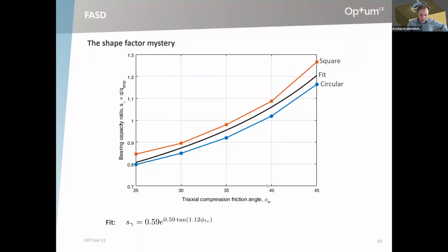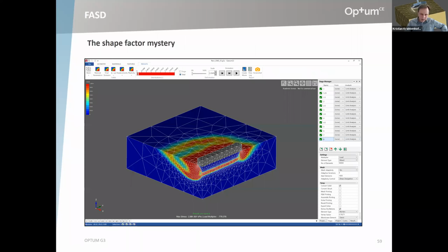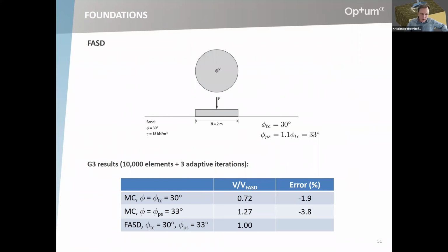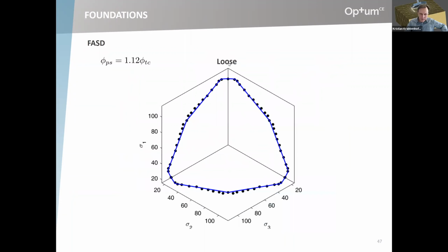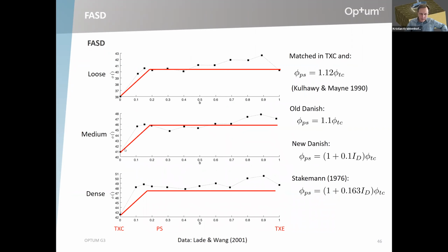Okay, then there's a comment that someone has carried out a lot of tests and gets the same friction angles. Again, you're welcome to contact us for a further discussion, but this type of trend, with the triaxial compression angle being smaller and then the friction angle gradually increasing, or abruptly increasing you could even say, is a very consistent trend that you see in lots of other experiments.